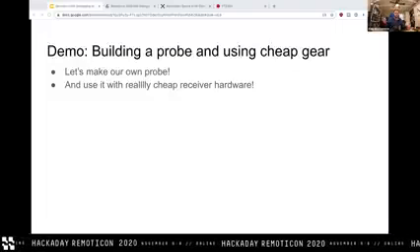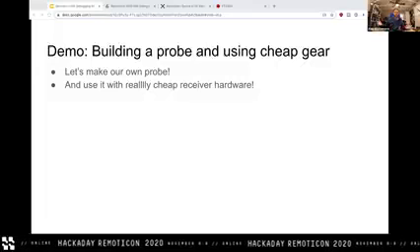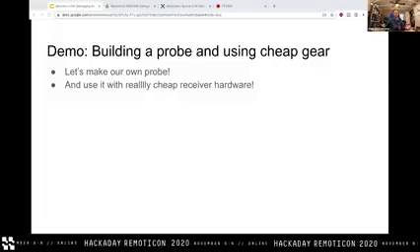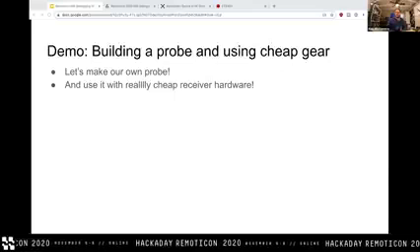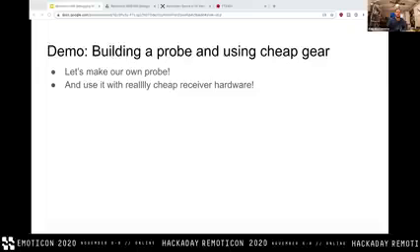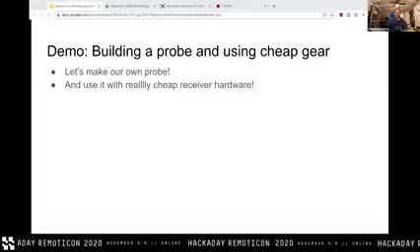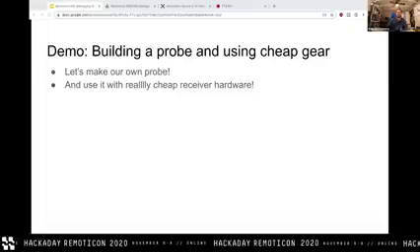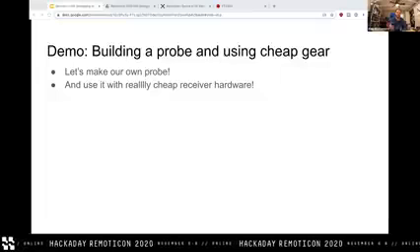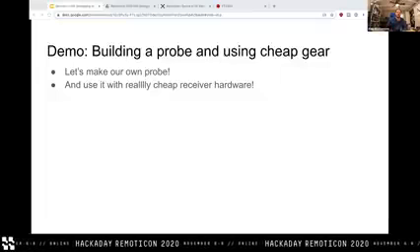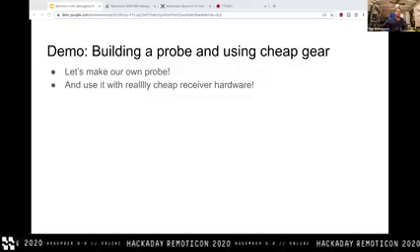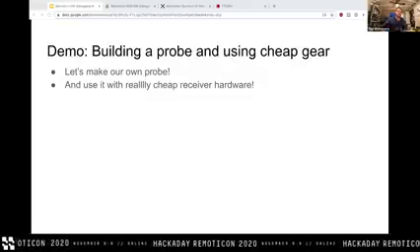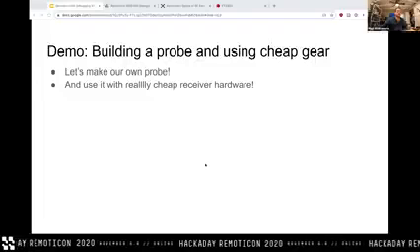It turns out the Ethernet subsystem on that chip operates at 250 megahertz, and there are a bunch of different analog voltage rails and conditioning pins where 250 megahertz is coupled very strongly onto them. So if you have large loop areas and long traces and decoupling capacitors that are not super adjacent to the pins and that sort of thing, that's what you end up with. Oh, and I'm actually on my last slide anyway, I guess.